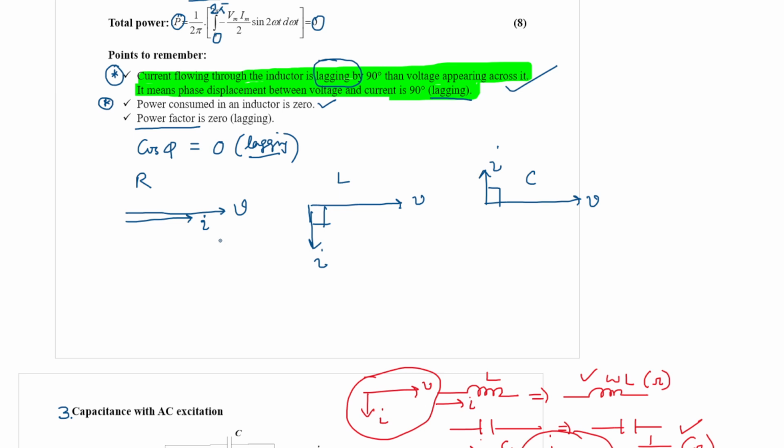It is not possible as well to draw to scale. However, the phase angle relationship between different phasors is shown. In case of a resistance, the magnitudes of voltage and current are not important, but the angle between voltage and current is zero.